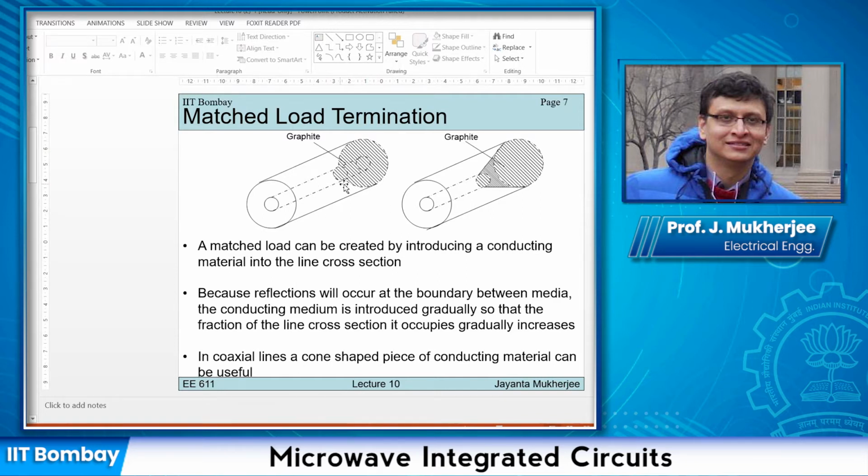Okay, but this is not a good way, because in microwave engineering, anytime there are sharp edges or sharp turns, like here, this inner conductor directly connects to the disk, which is not a good design process in microwave engineering, because anytime there is a sharp edge or abrupt change, that will cause reflections.